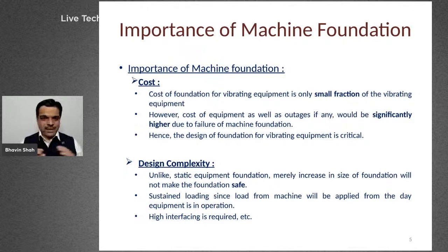The second most important part is that whenever the equipment is placed on the foundation, from that point onwards, sustained loading will be applied on that foundation. That means the load application will start from day 0 after installation of the machine, and that loading cycle will continue to be applied in a cyclic nature for the life cycle of the entire plant.